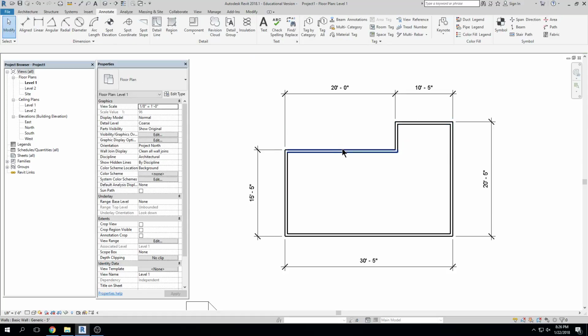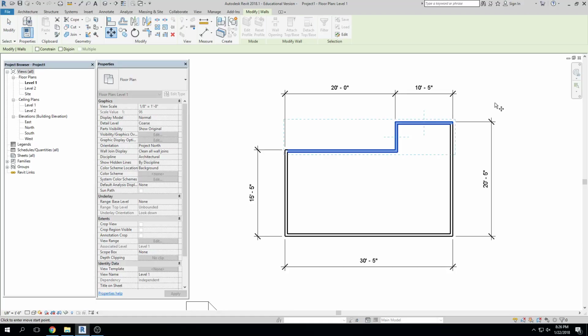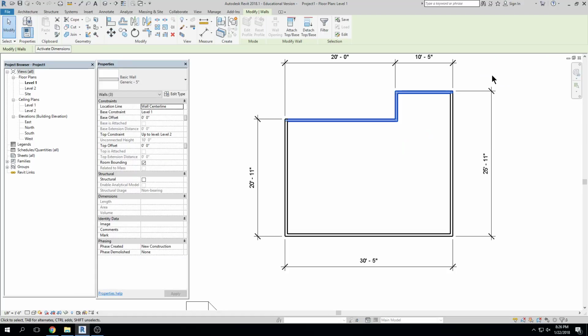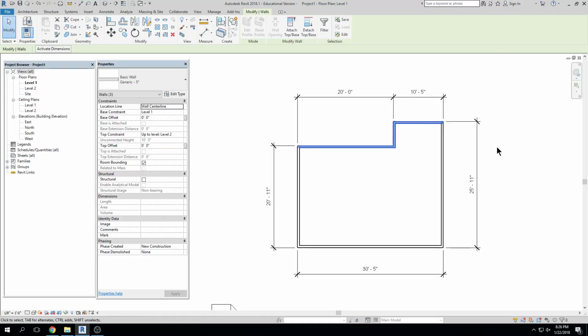So if I want to select these, I would click on this top wall. I would hover over here. I would hold down the control key, click. I'm still holding control, click again, and I've selected those top walls. Okay. I want to move. MV. I establish a base point or a point from where I'm going to start the move. Click. Move in the direction I want to go and type in a dimension. Or you can see over here by my mouse, visually I could say, oh, there's my 5'6" that I wanted. Click, right? Very easy. Let me rock the AutoCADers' worlds, right?